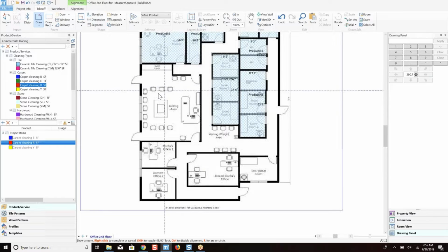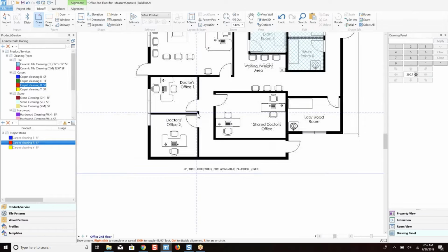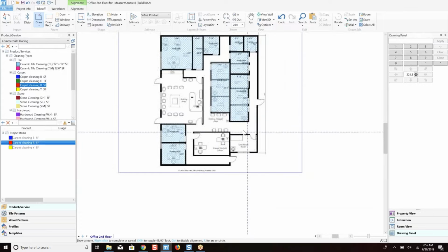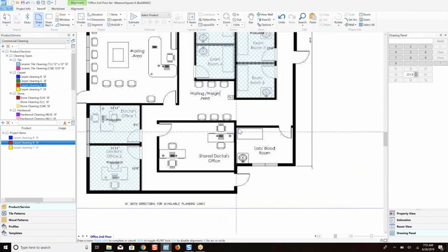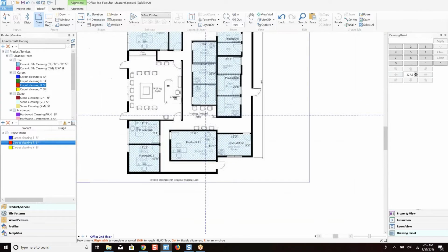And now when we get to the more quote unquote odd shaped rooms like this, we'll do single clicks to accomplish that. So I'm just going to do the basic shapes first, which is generally a best practice for us. And I'm doing more of the outside rooms first because I don't want to go through and click through all this hallway area. So the way I'm doing this will make it go much faster by being able to use our autocomplete tool, which is very helpful. So again, I'm snapping to each room when I see those green highlights. That's a good thing. I'll left click and hold when I see those to start drawing.